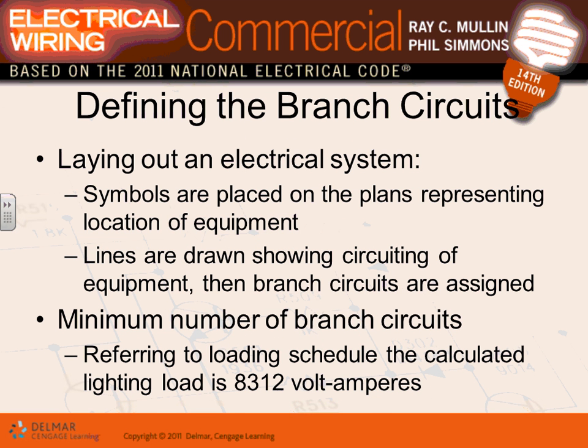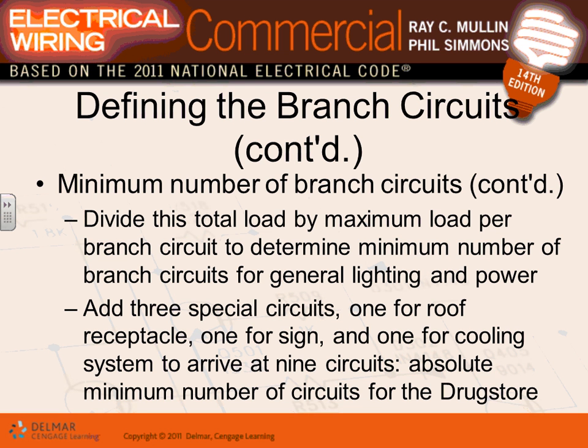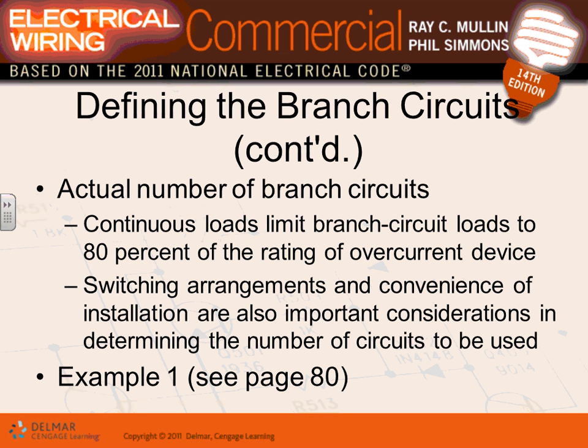Here's a fun thing. You can take the volt-amps of the lighting of your building, divide it by the voltage, and divide it by 20, and that will get you approximately how many lighting circuits you need for this building. One more time. You take the volt-amps of your lighting panel, divide it by 120, because lights are burning at 120, divide it by 20 amps, and that will get you the number of branch circuits that you need.